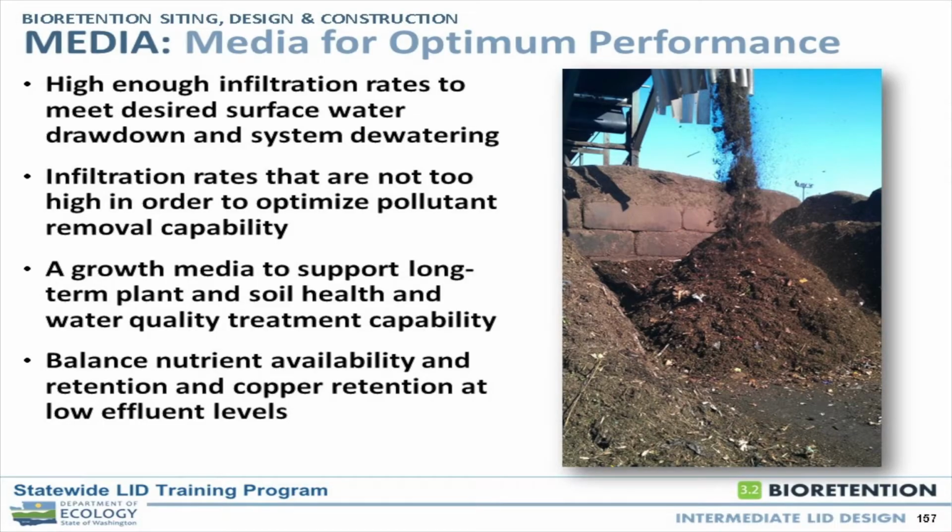Infiltration rates that are not too high so that you get adequate pollutant capture. And that makes a difference. The residence time of that water in the media makes a difference as far as how well it performs. Although, I will say this, a lot of the media we're working with now is high flow media, 50, 100 inches per hour, and we're still seeing very good treatment. Nevertheless, there is a maximum infiltration rate that is now prescribed in the Stormwater Management Manual, and we'll talk about that.